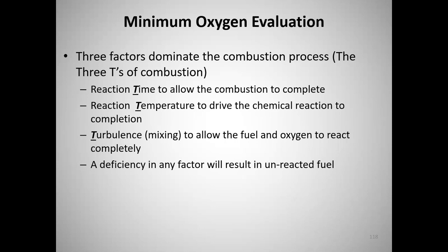So you've got to have that fuel and oxygen together for enough time at enough temperature, and then for it to oxidize. And then we have to have good mixing. We have to have turbulence to keep all of that stuff mixed up so that I have oxygens in close proximity to fuel molecules so that they can oxidize. So a deficiency in any one of those factors will cause your combustion to suffer. So time, temperature, turbulence, 3 T's of combustion.